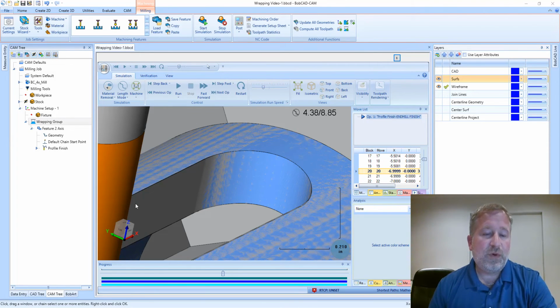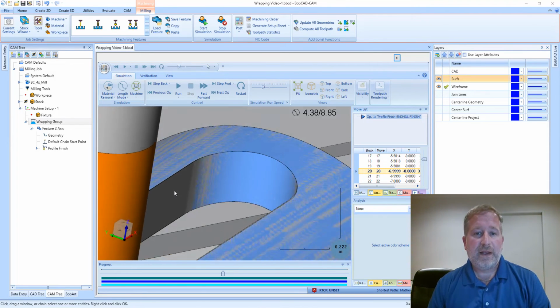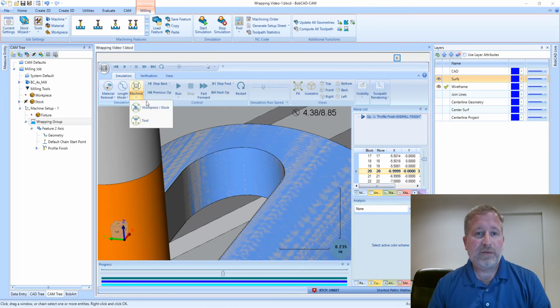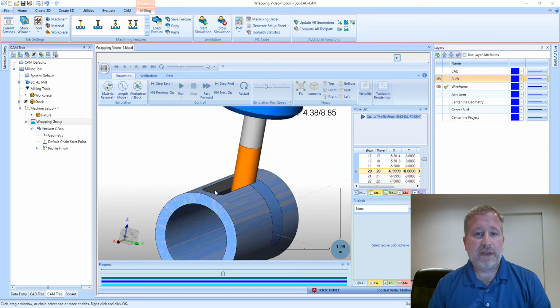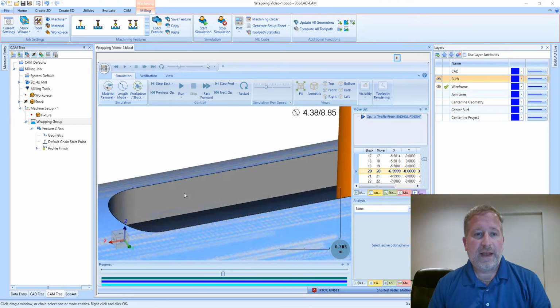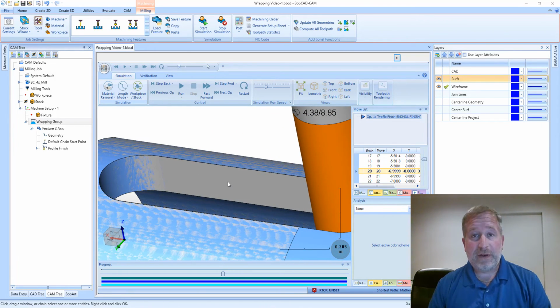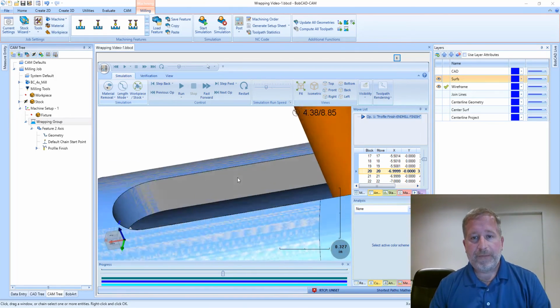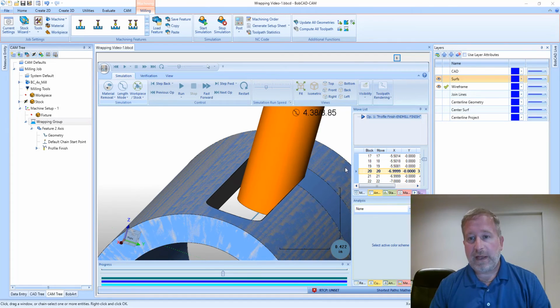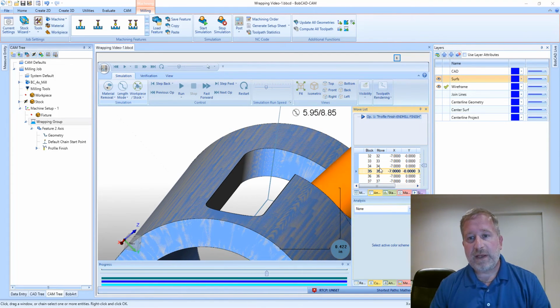So being that this wall is solid gray is telling me that we may be running into that workpiece. And looking at the other side as well, I can see that the same thing is happening on that side. That's because we're making those two passes. And again, based on the tolerances of your part, that may be acceptable.